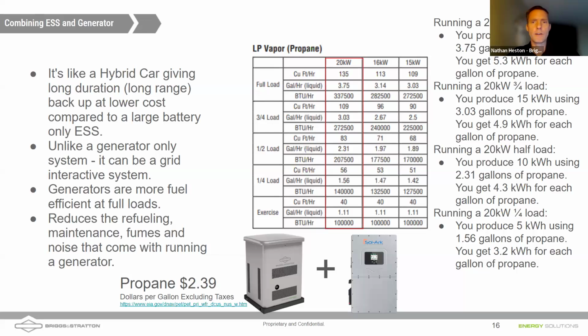Daniel, what are we looking at on the screen here, and what do we want to talk about? I think some of the takeaway here is that when you are running a generator, most of the time you're going to have maybe a 26 or an 18K generator. A lot of times the amount of power that your home is consuming is nowhere near that amount. We oversize the generator for motor start load capability, for example.